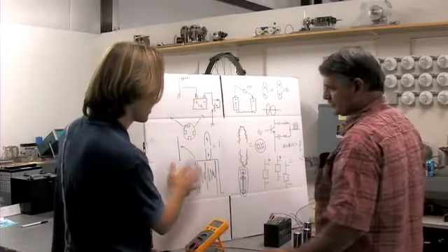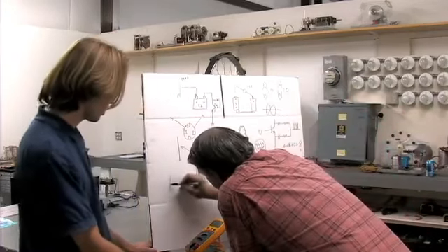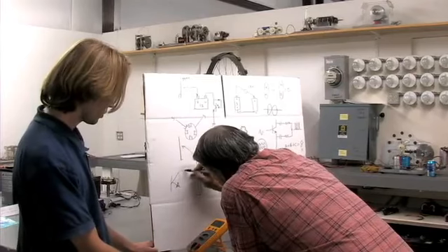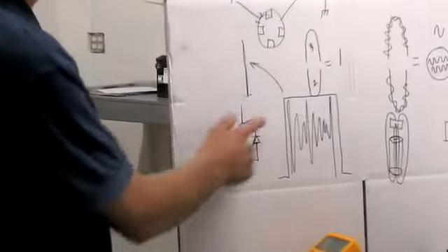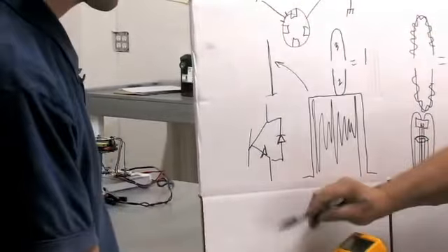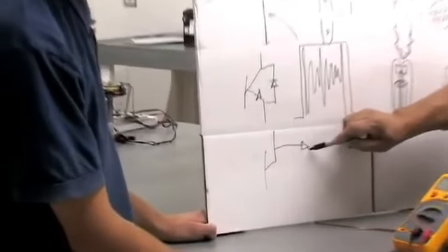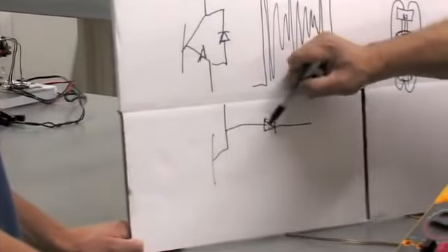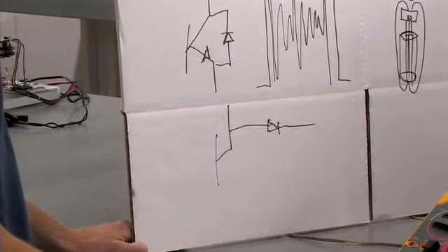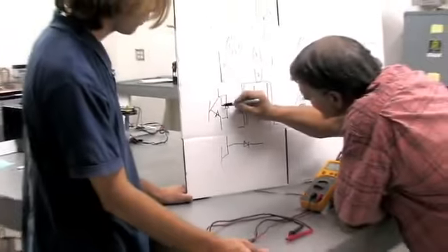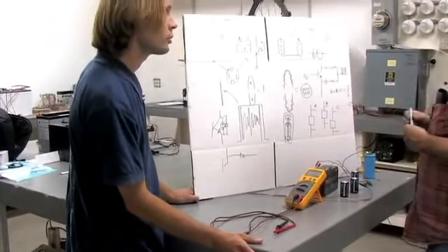So in conventional circuits, that all gets chopped off. Yes, in the conventional circuit, if they see that, they're going to short that out to protect this device. And that's shorted out across. But since I'm taking it off, I'm just catching the spike and sending it to the battery. I don't have to protect anything. If I want to protect this device, I'm just going to put a neon light here. I'm going to limit it to 90 volts.